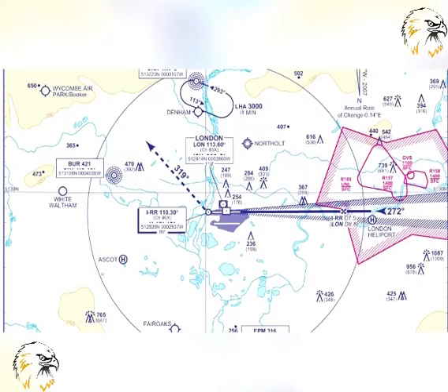It is implied that any approach procedure that is developed will not require the aeroplane to fly dangerously close to obstacles at any point during that procedure. Clearance can be obtained both vertically and laterally, but by requiring a pilot to fly the track accurately, the aircraft can be guided over a surveyed flight path, within the bounds of which all obstacles can be determined and assessed. Obviously, the area surveyed must have finite limits.